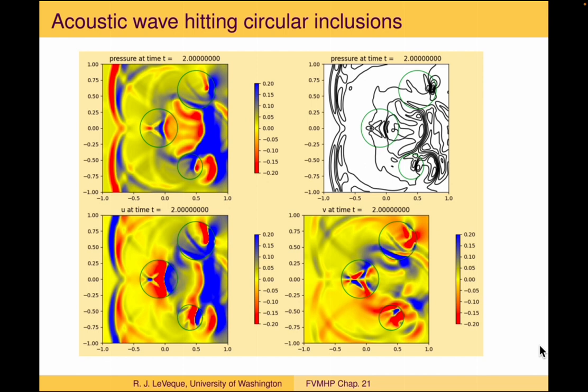And of course, with the addition of adaptive mesh refinement, you can really zoom in to look at even much narrower pulses of pressure or high frequency wave oscillations to some extent. If you have very high frequency oscillations and hundreds or thousands of wavelengths within your domain, then these effectively second order accurate methods wouldn't really be appropriate. You would have to resort to something higher order. But for many problems, you can get a fairly nice solution with these approaches.